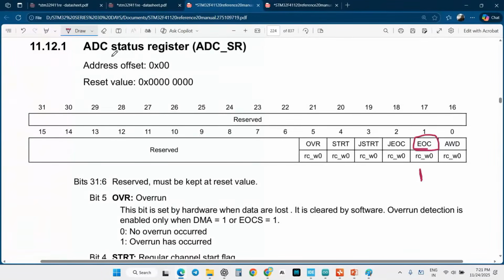First of all, I'm taking this SR register, which considers the whole register. I'm going to use the AND operator with a bit shifted left one time, because the one is set at the left. I keep on checking the condition.